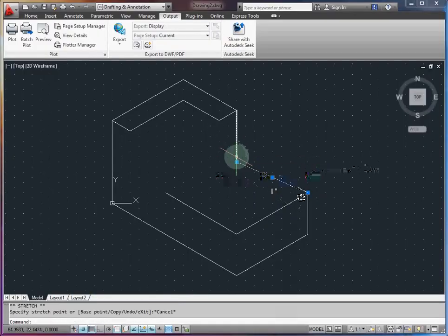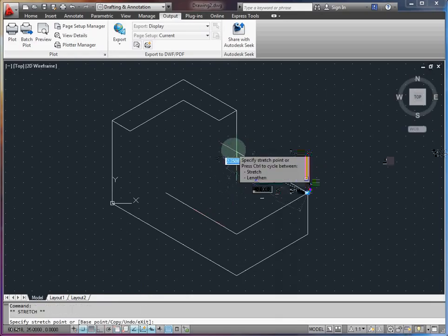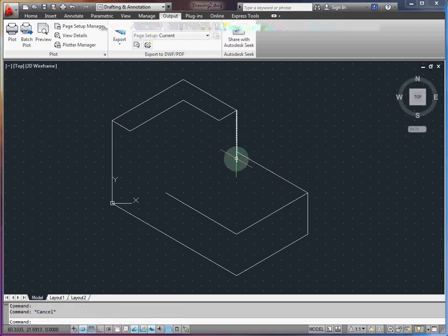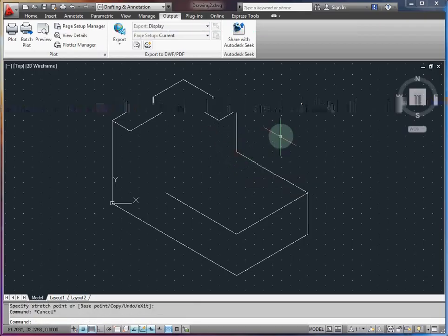I could manually drag this to the place I want, but again, I've got that same issue. You'll notice object snap is turned on and off with F3. So if I disable that now, then it'll neatly line up as I want it. I can also manually stretch lines out here and do a neat little fix.